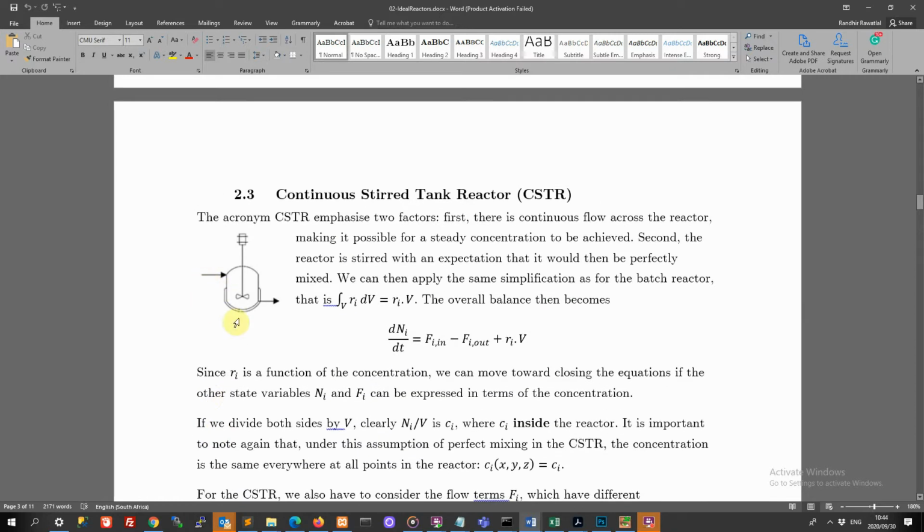In a flow system, we have said that there's a nice steady state if we assume the flow in and the flow out is equal. Now, if the pressure is dropping, then that's going to influence our flow through here, right? There's no magic instrument that's going to just keep the pressure constant here. Well, other than a controller. But for now, let's say we don't have a controller in here.